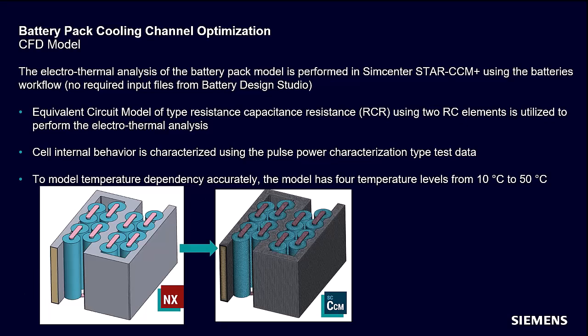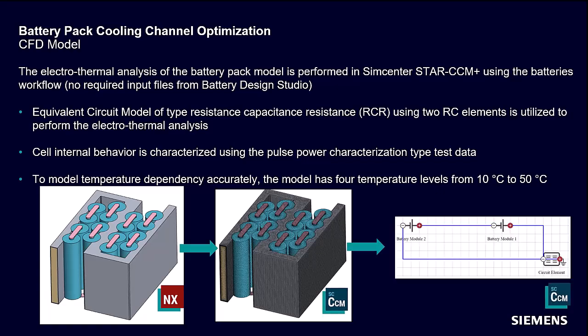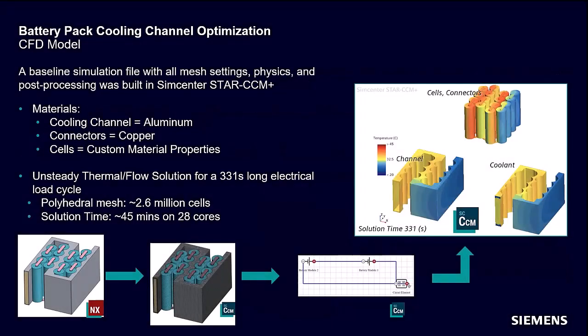The Parasolid geometry from Annex is imported into STAR-CCM+ to build an automated mesh pipeline and the battery circuit model. A baseline simulation file has been created using STAR-CCM+ for the purpose of being used as an input file in HEEDS. HEEDS via its STAR-CCM+ portal will update the entire CAE pipeline based on the modified geometry, run the solution, and extract results in an automated way.